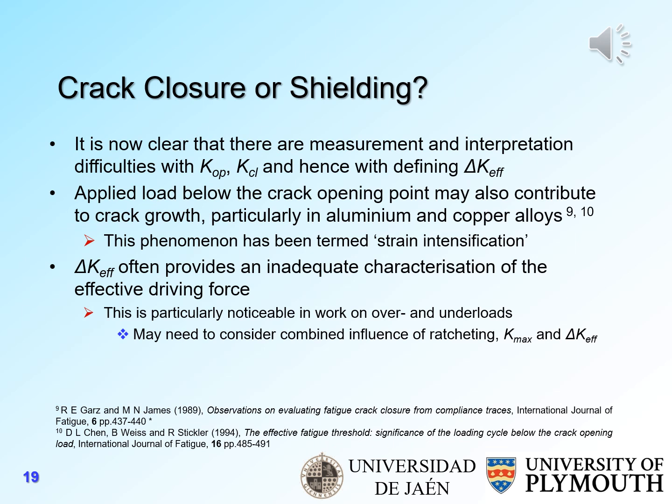So it seems to me, and indeed to others, that it's clear that there are a number of measurement and interpretation difficulties with K opening, K closing, and hence with the definition of any delta K effective. It's also clear that the applied load below the crack opening point may contribute to crack growth, both in aluminium and copper alloys, and I cite two references there, one some work I did years ago and another by Chen, Weiss and Stickler. And that phenomenon was termed by the latter authors as strain intensification.